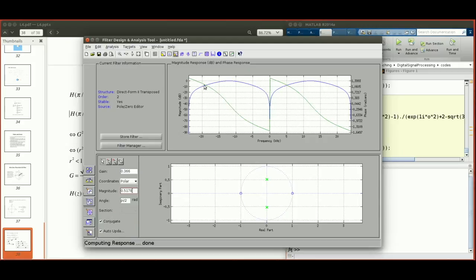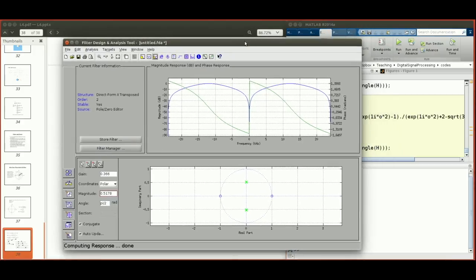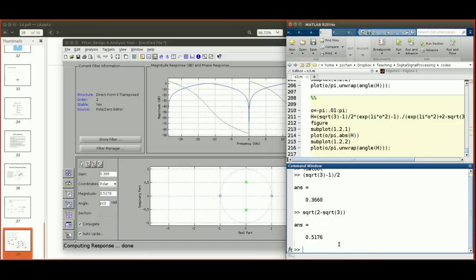That's going to be the angle for these two poles, right? So now you can see right away the amplitude and phase response for this particular two pole filter design. That's the amplitude response in terms of dB, and at mid frequency, this is in terms of kilohertz. It's not exactly in terms of the normalized frequency yet, but it doesn't really matter. In the mid frequency, you can see the passband, and at normalized frequency 0 and pi, the amplitude is extremely small. So that's the same as our previous plot, our own plot, right?